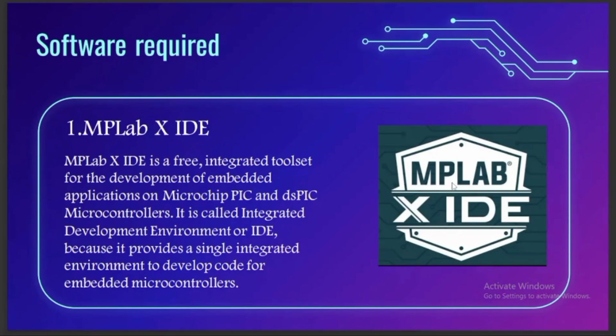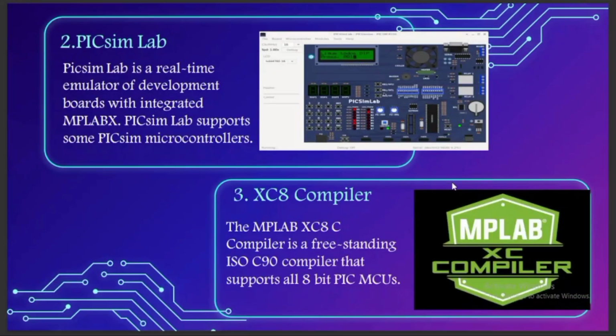Now, going to the next software, the second one is PICSIMLab. With integrated MPLab X, PICSIMLab supports some PIC microcontrollers. Here we can see the pictorial representation. It is the interface of the PICSIMLab. Now the third one is the XC8 compiler. The XC8 compiler is a freestanding ISO C90 compiler that supports all 8-bit PIC MCUs. Means it supports every 8-bit PIC microcontroller unit. We can see over here the logo of the XC8 compiler.